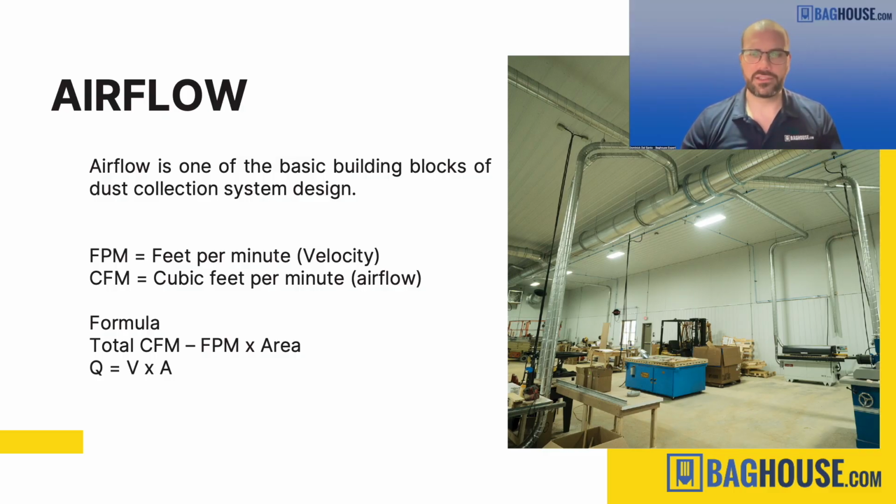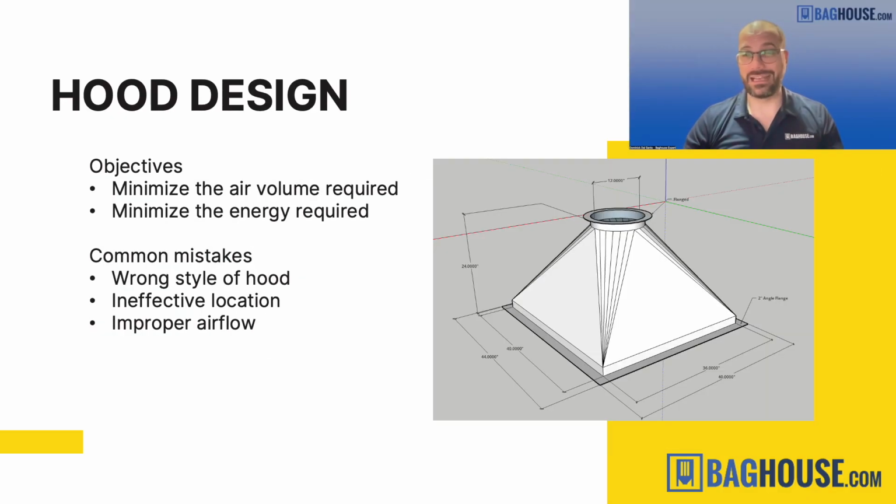Now, in most dust collection systems for woodworking, we have a little bit easier of a task ahead of us, because to calculate the airflow, what we need to do is figure out how many sources of dust we have. So in your application, it would be how many machines do we have that are going to make dust and need dust collection attached to them. And then we have to figure out how much dirty air that machine is making that needs to be removed every minute. So this takes us to the hood design or the ventilation design for each pickup.